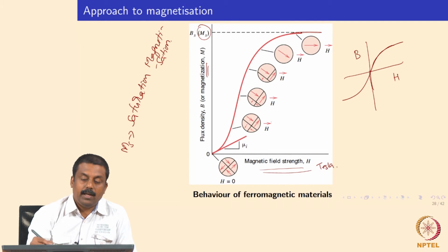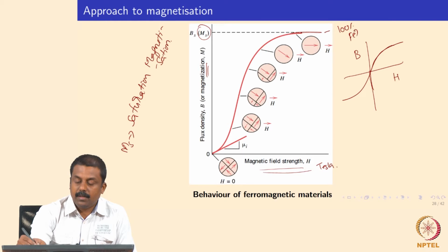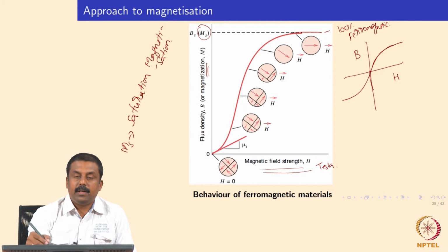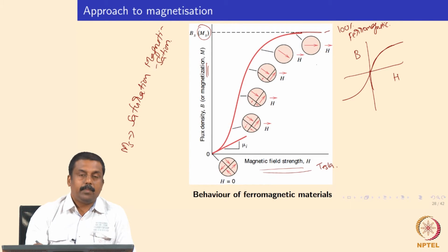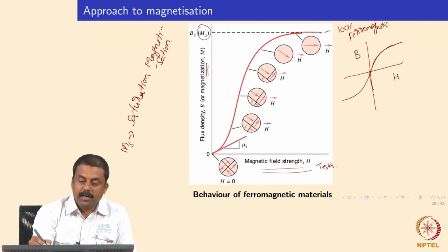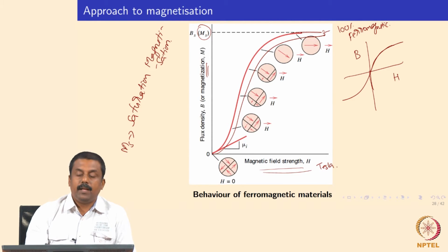For example, if you have a fully 100% ferromagnetic material, you have an MS value, say this value corresponds to a 100% ferromagnetic microstructure. Now you introduce retained austenite into this microstructure. That means you are introducing some paramagnetic constituent. So the magnetic saturation decreases. You may expect the saturation value to decrease compared to a microstructure with completely ferromagnetic constituents.